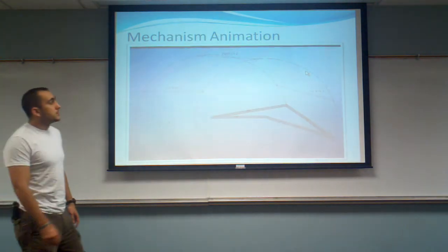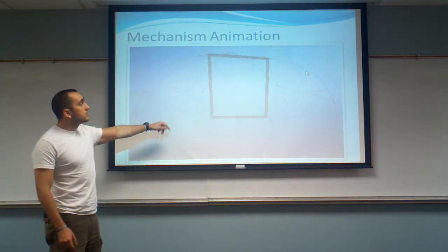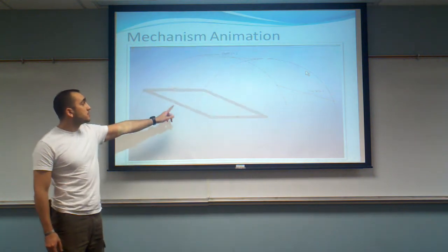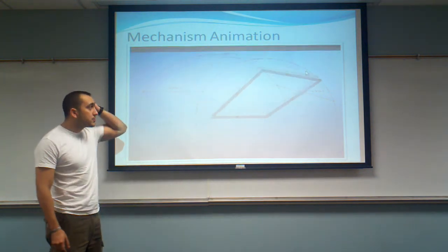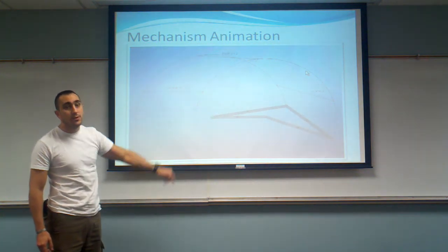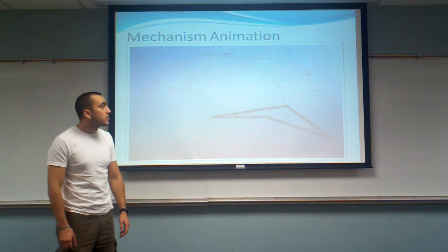And here you can see this is an animation of the motion as rendered in SolidWorks. I'll verify the information gathered in MATLAB. You can see the mechanism transitioning through all 3 points in sequence. And these arcs actually trace out the paths of points A and B along the coupler.